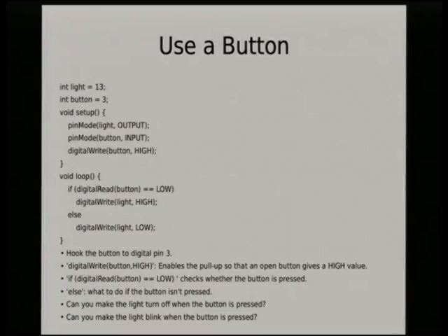So we talked about the buttons we have, which of course are just switches. They're not switches with a resistor, they're just switches. So in order to get the button to work at all, I had to go through usually about 15 minutes of talking about a pull-up resistor. And that was a mystifying notion. Why would you need a pull-up resistor in this environment?